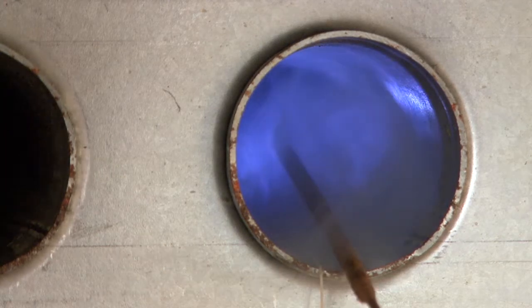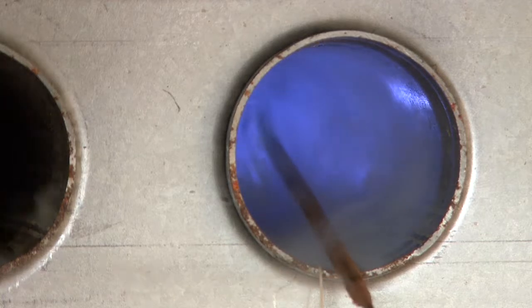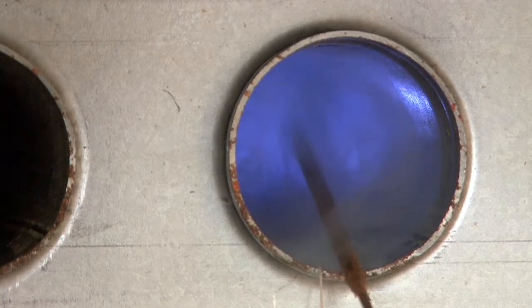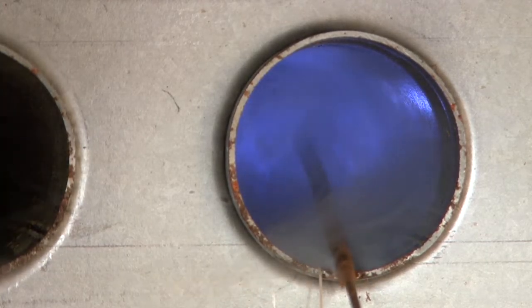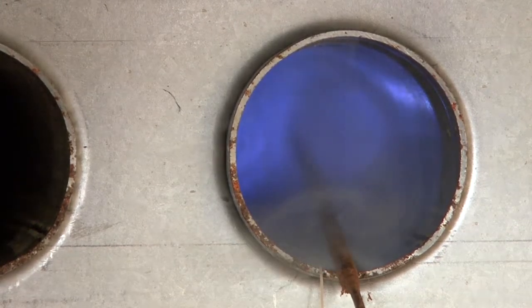But so far with this heat exchanger, I'm happy. Since I've got it apart, I might as well go through and do all the tubes. But for the purpose of this video, I just wanted you guys to get an understanding of how to do it. So that's pretty much it. If we go through each cell and we don't see any disturbance, then I would move on to putting the thing back together, because in my opinion, the heat exchanger is definitely not the issue if you're not getting any impingement to that smoke.